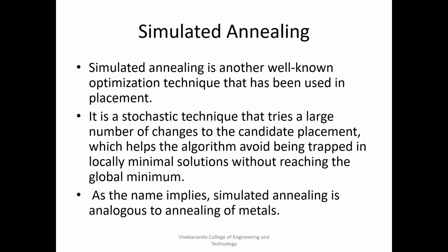This is an iterative placement method. In each iteration, some logical elements may be moved based on certain parameters set by the annealing temperature. Exactly where a selected element moves to depends upon the details of the placement algorithm.